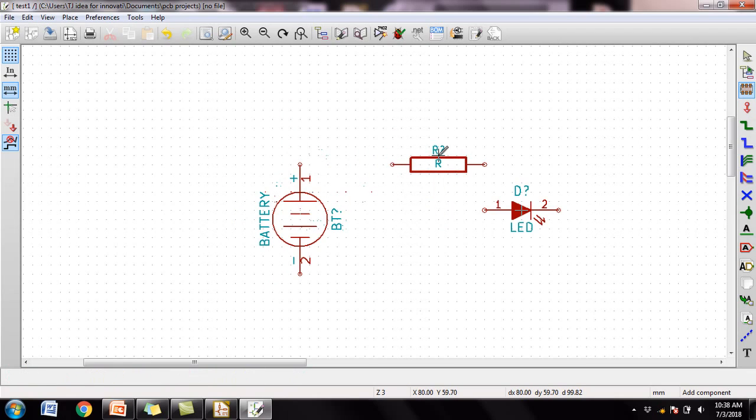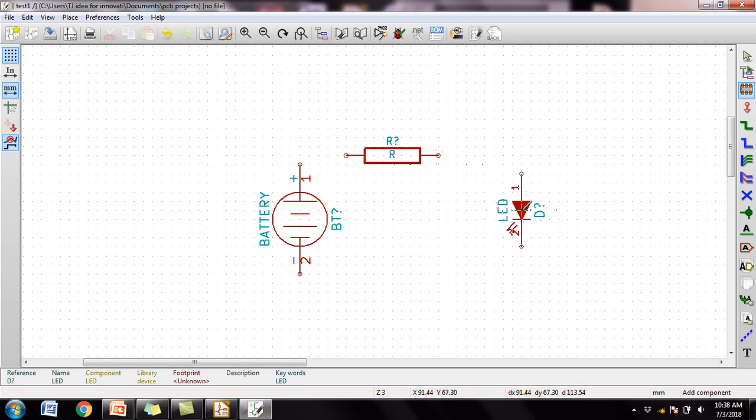Again, for the resistor also, just move that. Okay, then done. So let us move this, rotate. Okay, done. Now the part is drawing the tracks, that is making the connections between the terminals. For that you can use place a wire. Click on that and start drawing the wires across each terminal.